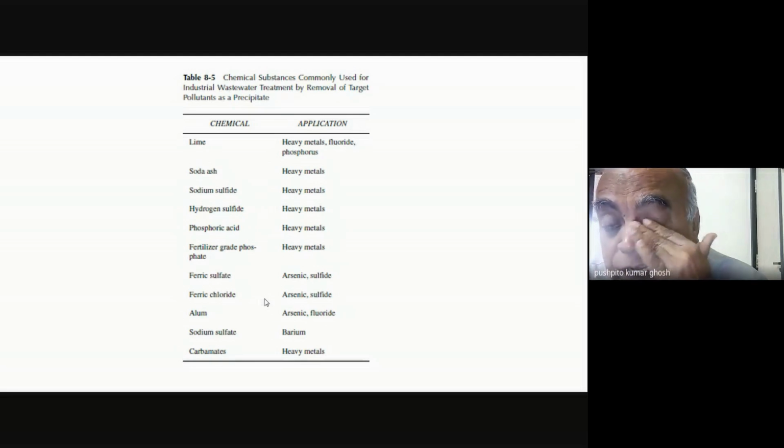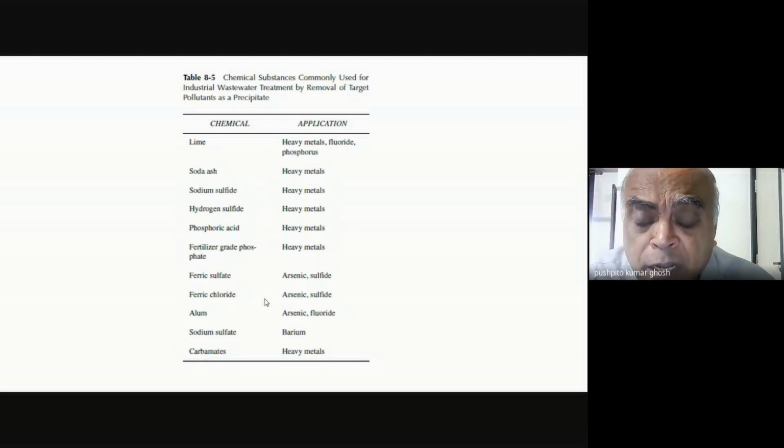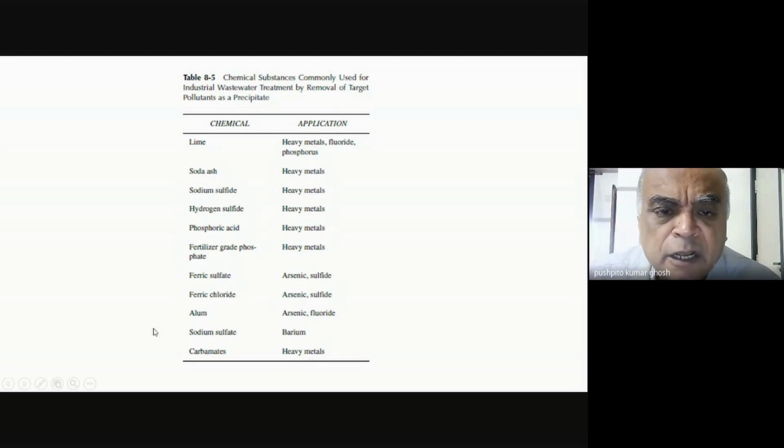Okay. Also remember that if I want to precipitate out something, obviously I can't look for very fancy chemicals to precipitate these things out, because your amount may be in ppm, but your volume could be very, very high. And I have to well exceed my solubility product. Otherwise, I can't precipitate out something. So firstly, I have to find things which will give, as a result of the addition, a very, very low solubility product of, let's say, mercury sulfide. It has a very low solubility product. So I can add only a small amount of sodium sulfide and it may do the job.